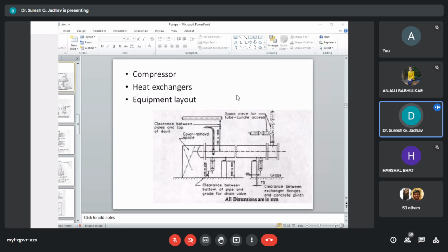The working space should be kept clear of any piping and accessories. We have to consider their respective arrangements for particular accessories to facilitate channel, shell bore, and tube bundle removal as well as maintenance and cleaning.